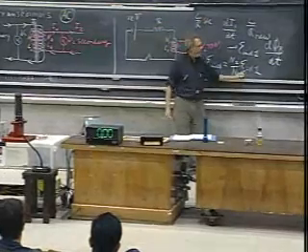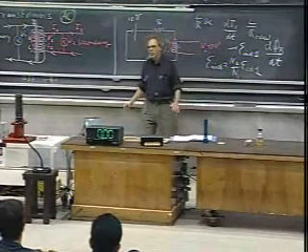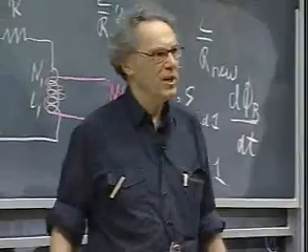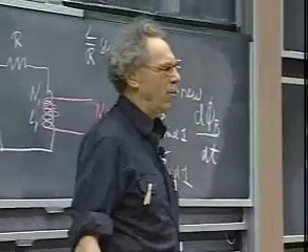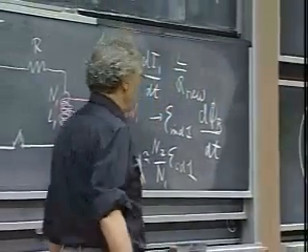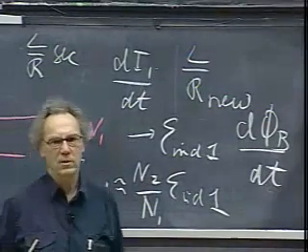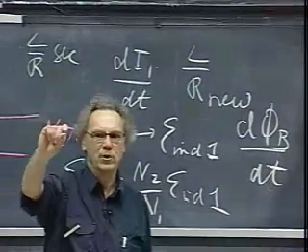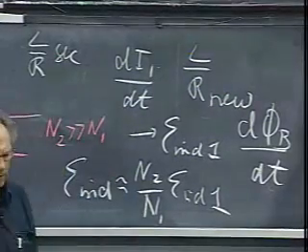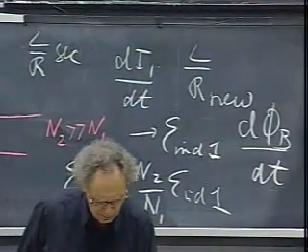So now I get in the secondary an absolutely horrendous potential difference. I could get up to 1,000,000 volts if I want to. In your cars, that is not necessary. It is enough in your cars that you get here something like 10 kilovolts. And that will comfortably give you a spark over your spark plug.